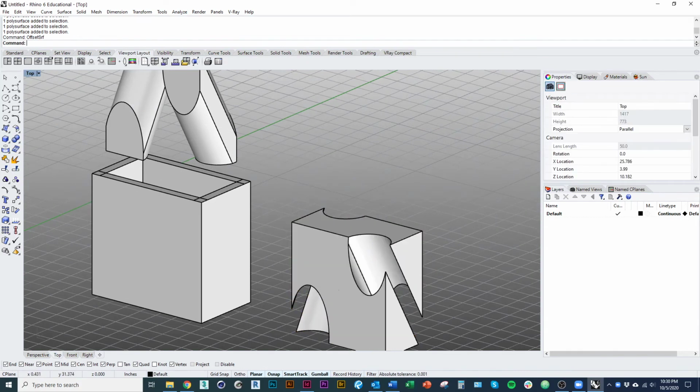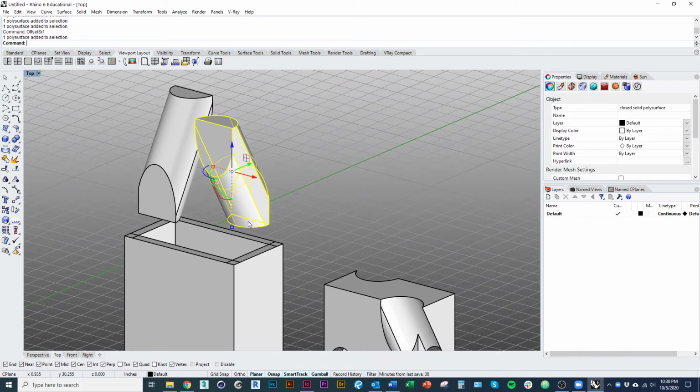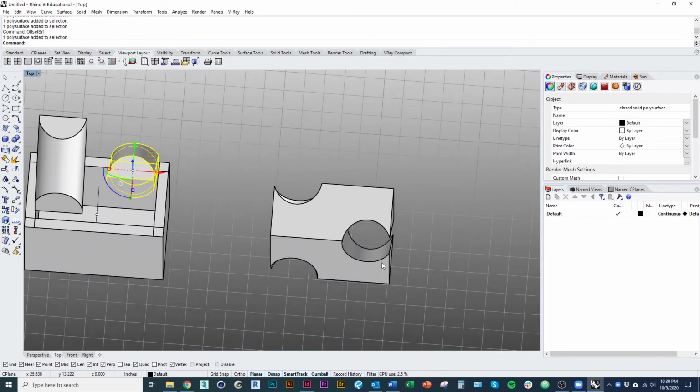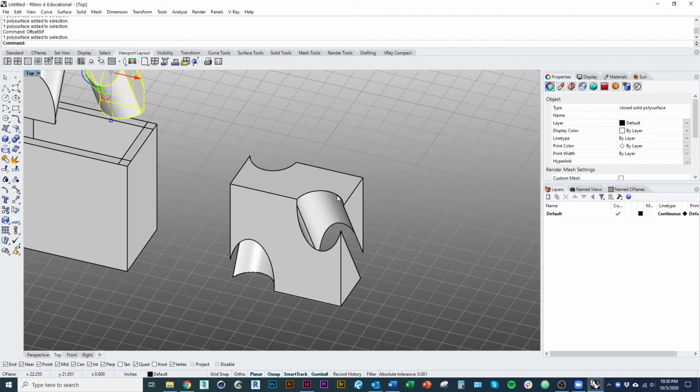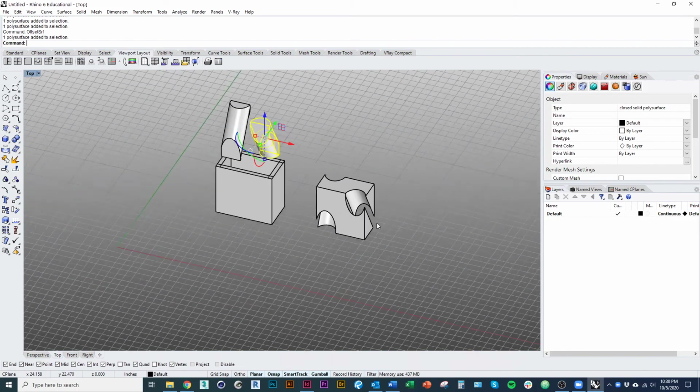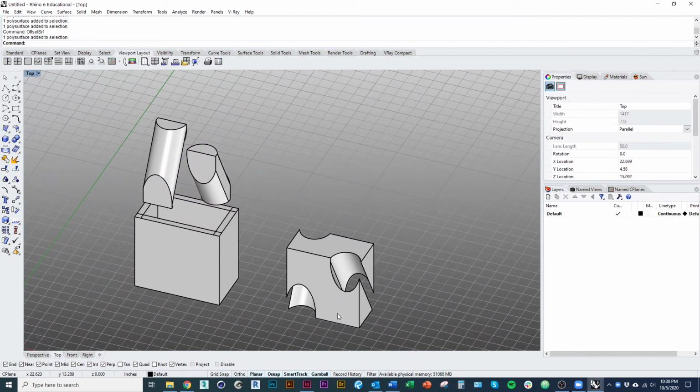And the beauty of using either case, the wax or the foam, is that we can kind of destroy it to get it apart. So you might imagine that if it were a sphere, for example, it would be like encased plaster. So how do we get that thing that we use to make that void? How do we get that material out? Well, we can cut it. We can melt it if we need to, with the wax, for example, and we can work it out. So even though it might be something that plaster is poured all the way around, we can still figure out how to cut it out of the shape.